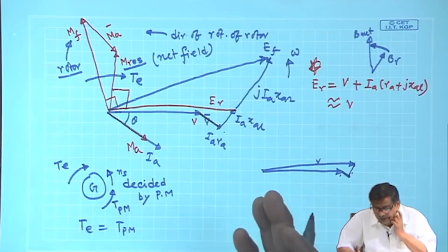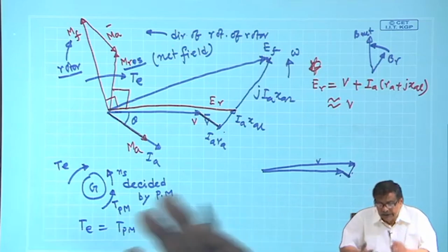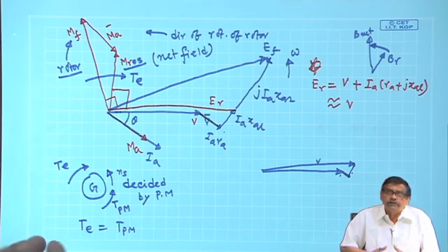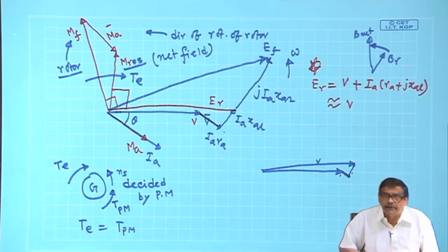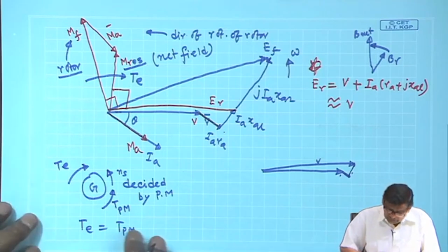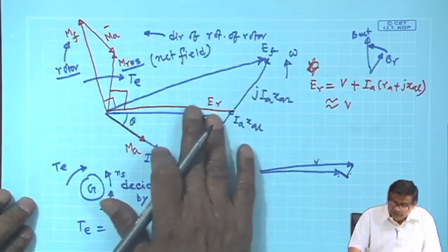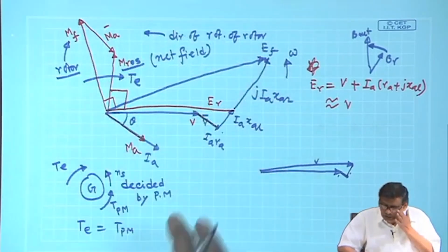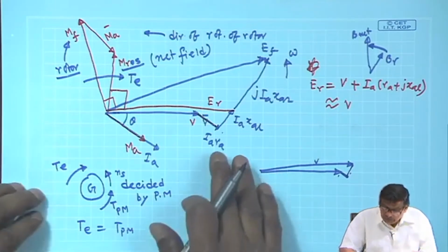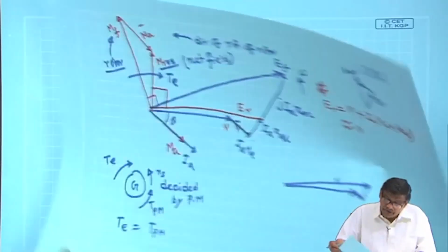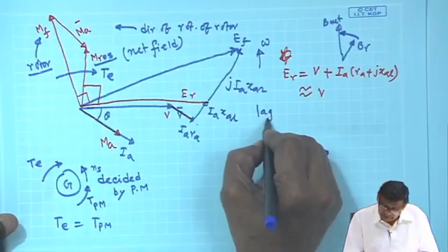If it is a 4-pole machine, the rotor speed of the synchronous machine will always be 1500 rpm if it is fed from a 50 hertz supply. So, this is the steady state thing, and this will be the complete phasor diagram. We will draw the phasor diagram for synchronous motor operation also, but before that let me draw the phasor diagram. So, this is for lagging power factor.